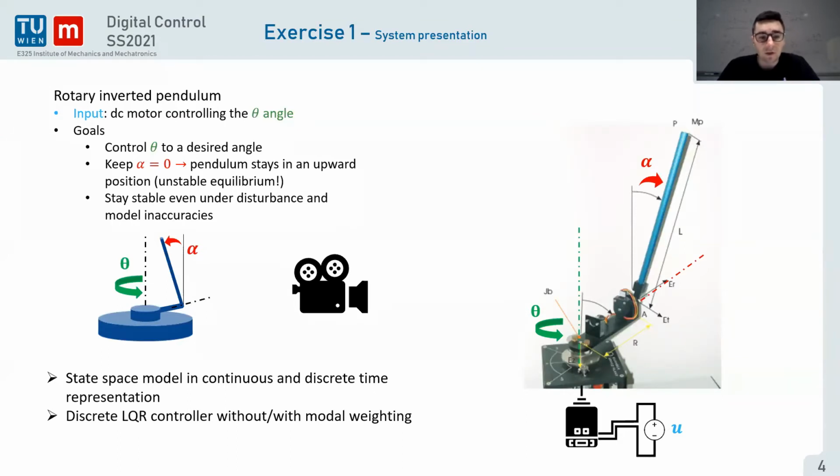We're going to see that an LQR controller, or a discrete LQR controller, also called dLQR, is nothing else than a state feedback controller, where the gain K is defined differently. It's not defined to ensure some closed loop pole location, but is defined differently. And finally, we're going to need, of course, an observer. This time we're going to look at the minimum order observer, and I will show you a small comparison between this minimum order observer and the current and predictive observer we did last time.